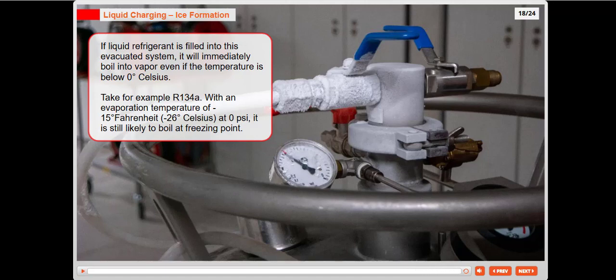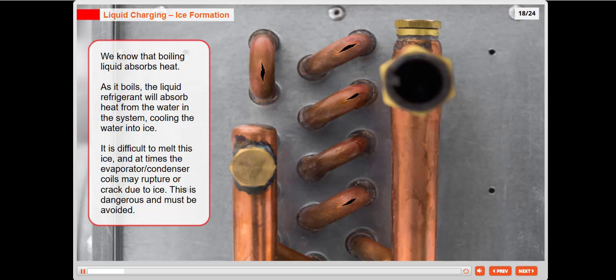We know that boiling liquid absorbs heat. As it boils, the liquid refrigerant will absorb heat from the water in the system, cooling the water into ice. It is difficult to melt this ice, and at times the evaporator or condenser coils may rupture or crack due to ice. This is dangerous and must be avoided.